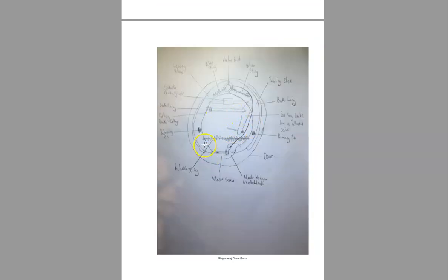This one here, again, that's well labeled, but I have shown in the past some standards for what is an acceptable drawing. This circle is maybe a little out of what I would say is comfortable for a freehand drawing. It's borderline. Best case scenario is borderline for not losing a mark, but it's well labeled. It's really important that you label your diagrams. This is for everything you do in engineering. One thing it doesn't have is feathering. I really hate feathering. But it's a freehand sketch. It doesn't need to be perfect. I would just say, when you draw this initial circle, if it looks more egg-shaped than circle-shaped, maybe take a second attempt.